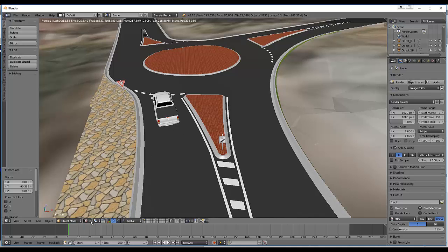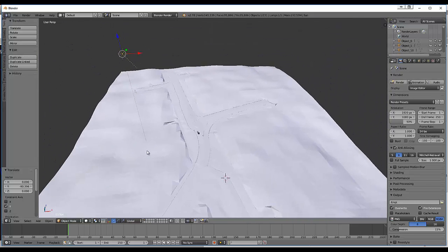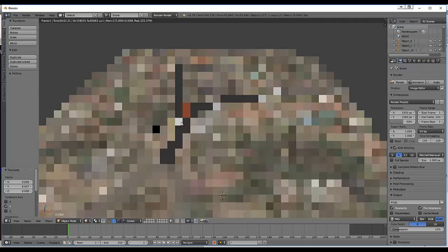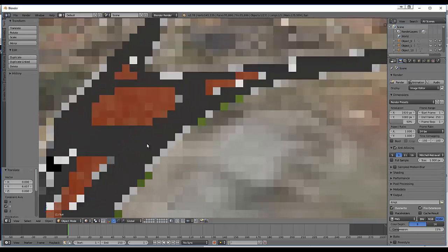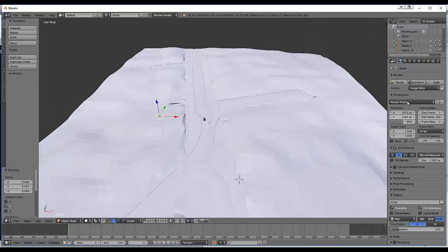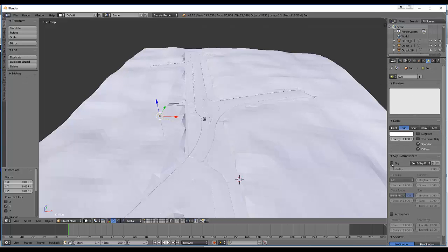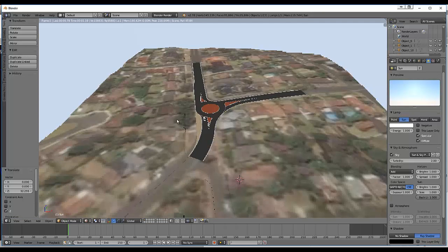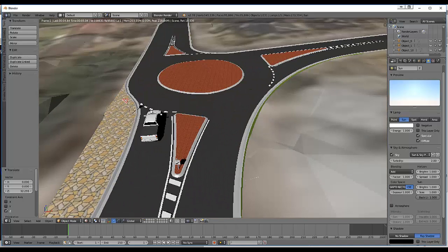Let's go back there. In fact, I might just lower that a little bit and push it out that way. Although that didn't affect the shadow too much. Anyway, obviously though, depending on where... Oh, no. I know why. I haven't set up shadows yet. So, sorry, if I click on that sun, I click on the sun option to the right, I need to turn on sky, and I need to turn on the shadow. So that's important. Let me just increase the height of the sun. So now if we go into rendered, we should be casting shadows, which we are. You can see the shadow on the sign and the vehicle there.